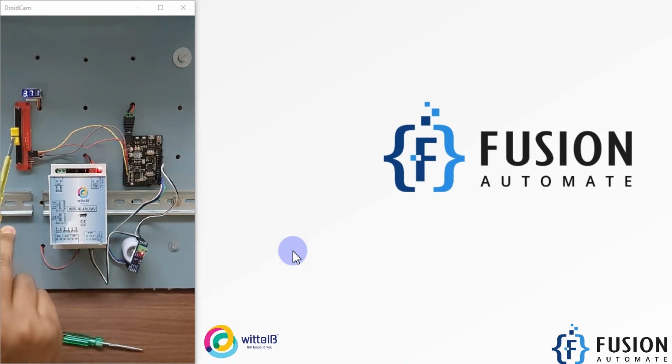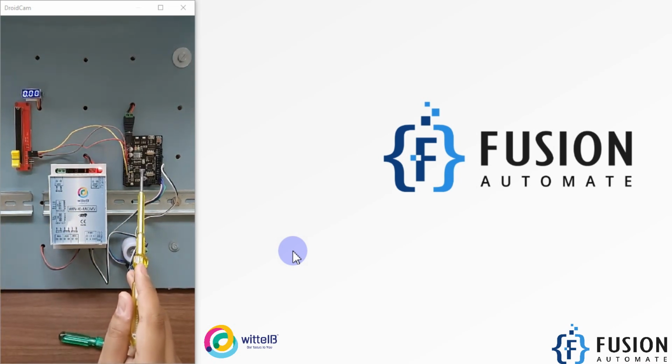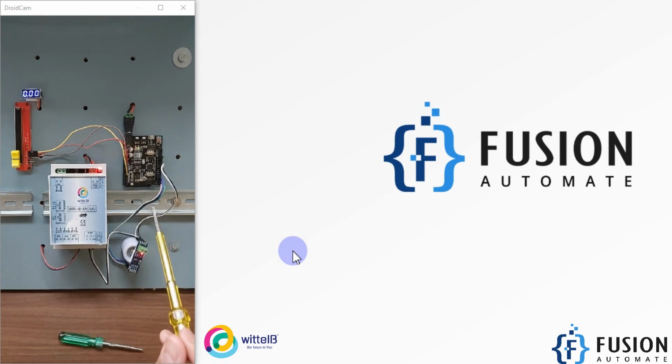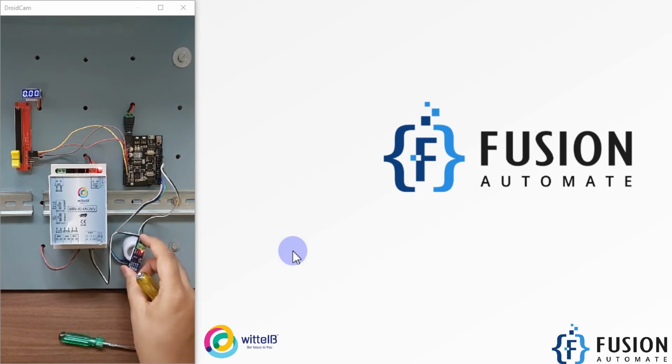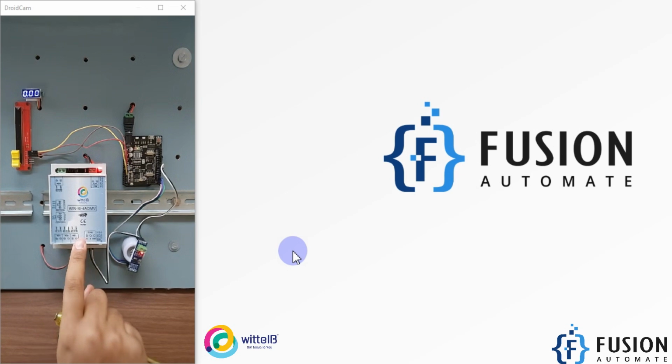If I travel all the way up, you can see 8.11 volts, and if I travel all the way down, you will see 0 volts. So the potentiometer provides the reference to Arduino. Arduino will convert that data into Modbus serial, or Modbus RS485 protocol, using this converter, and the converter will send the data to this Modbus IO card over RS485 communication. Based on that data, the analog output will vary.